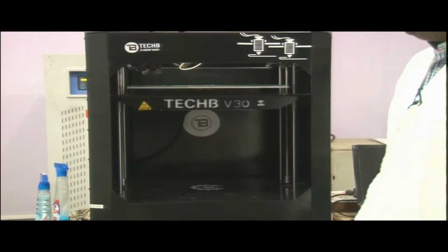The precision and smoothness of the printed models is also influenced by other factors such as the bonding force between the layers, is it lower or is it adequate, then the weight of the upper layers that squeeze upon the lower layers, and printing problems like warping, misalignment, shrinking, shifting of layers. These printing defects might be there, all those things could be there.